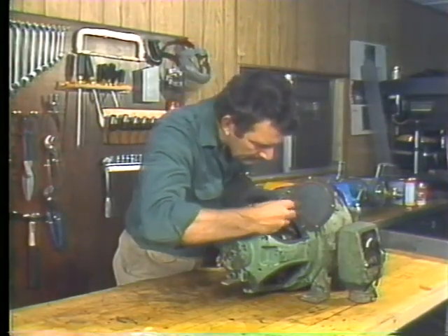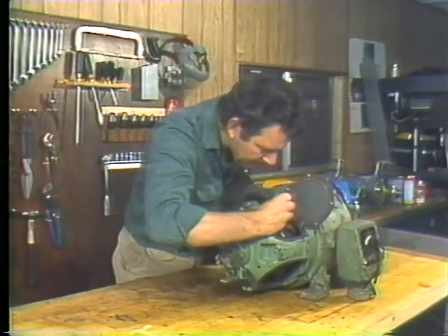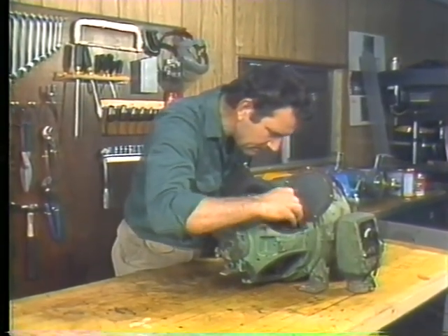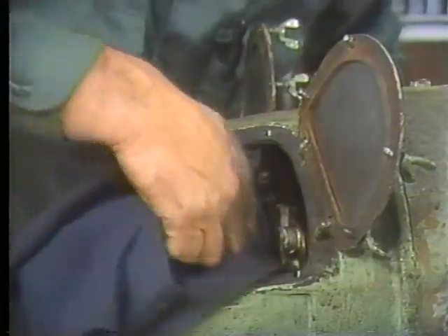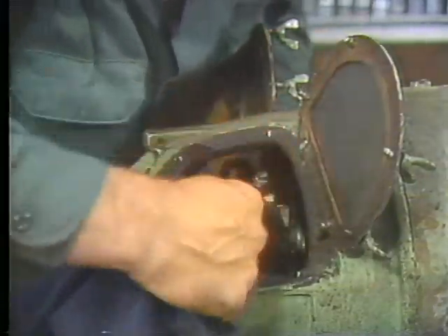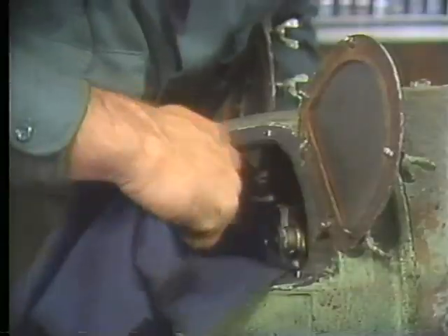In fact, cleaning the motor thoroughly is the first order of business in any maintenance procedure, and we'll start doing that now. Then we'll inspect each part as we go along for the problems we just mentioned. Open the inspection covers and vacuum the interior of the motor as thoroughly as you can. Then take an approved cleaning solvent and some clean rags and wipe out the interior.